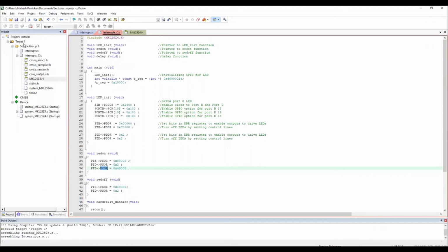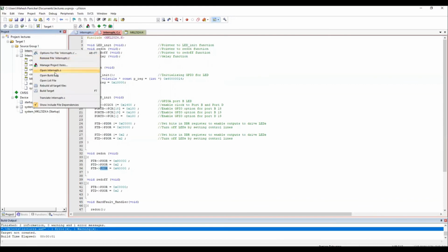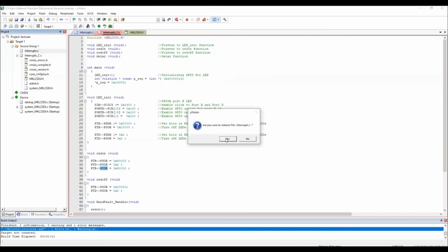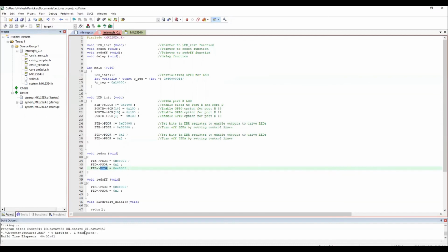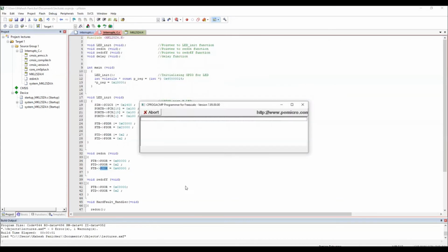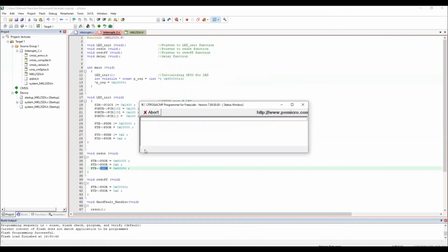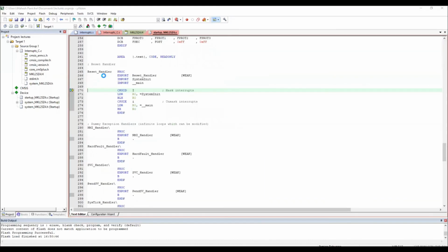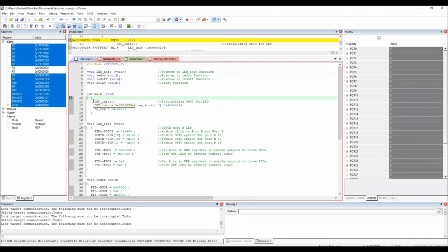Okay, so let's go and debug the same so that you understand it. Let me just give you 1 minute. It will create an error because it has 2 files in it, so I have to remove this file. Go ahead and remove the assembly language file, and compile it again. It's good to learn like this, right? Some errors you'll always learn from. Go to debug, connect. Same. The only difference will be that it will come to this location. Rest everything is same.